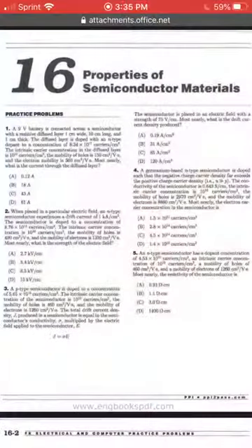I'll explain it a little bit, but for now, the steps that we are currently undertaking to solve this particular problem are somewhat the same as problem number 1. So pn is going to equal ni squared, but once again, p is missing. And if you crunch that into your calculator, you should get an answer of about 1.14 times 10 to the 5th carriers per cubic centimeter. Once again, we've got to find our conductivity.